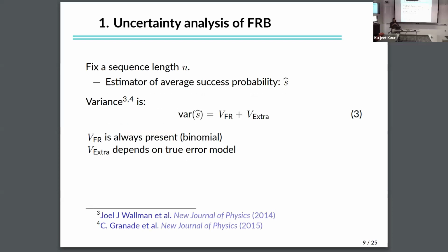So at least in the experiment that we collaborated with, loading things really means getting stuff onto their FPGA that generates their pulse sequences. It's a microwave experiment, so the FPGA controls the microwave drive they use to actually perform the gates. If you want to load everything in ahead of time, you have to get all this information about the random sequences onto the FPGA. And that's the thing that can be very time consuming: loading a pretty large amount of data onto this FPGA quickly. It's not really designed for that.